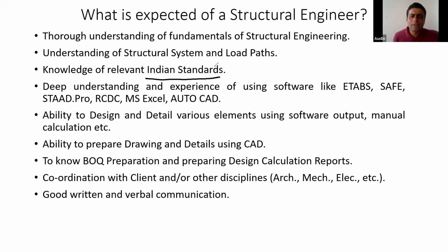So develop this habit: try to read the Indian standards, and also search for unknown standards and just learn from them. From the Indian perspective, IS 456 is required, IS 800 should be understood, IS 875, IS 1893, IS 13920. These are some of the basic design standards that you should be aware of.